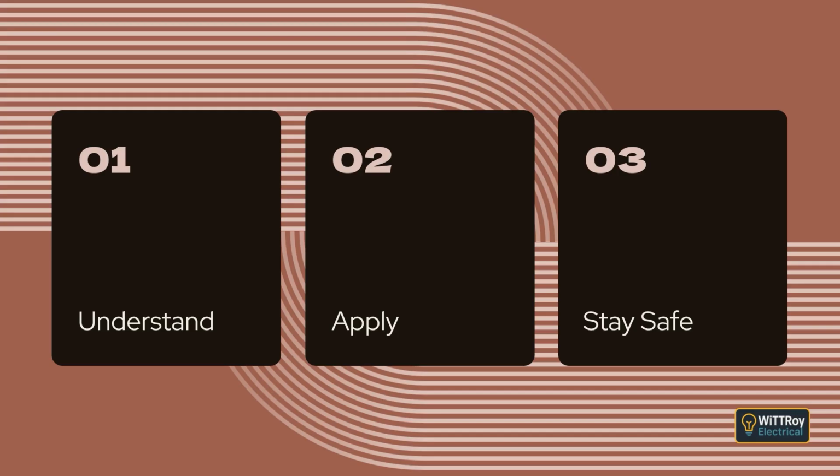Clause 2.9.2.1, General. Switchboards must be installed in well-ventilated places. They must be protected from moisture. They must also have enough space around them so electricians can install, test, maintain, and repair equipment safely.